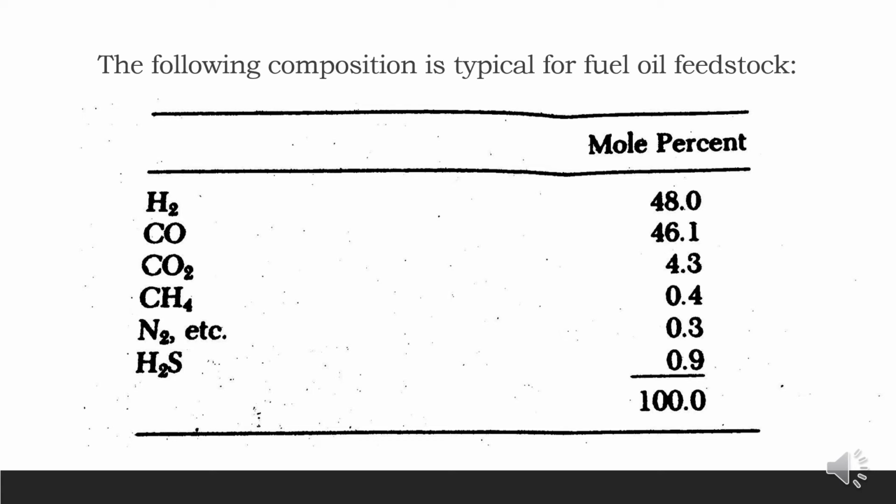The product gas is cooled by a direct contact water quench followed by a water scrubber and a filter. All of these serve to remove unreacted carbon from the product gas. The carbon is removed from the quench water, for example, by filtering for disposal or reuse, or it may be discarded as a water slurry.